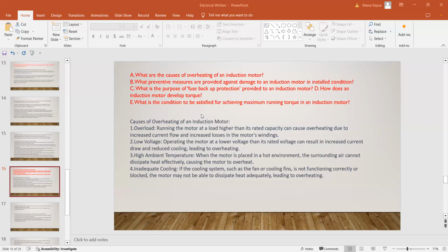Instead of low viscosity fluid, you are putting high viscosity fluid. Obviously, there will be more load on the motor. You must have seen this on the transfer pump when you are changing over the tanks. The amps increase.